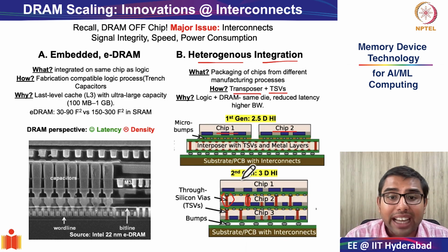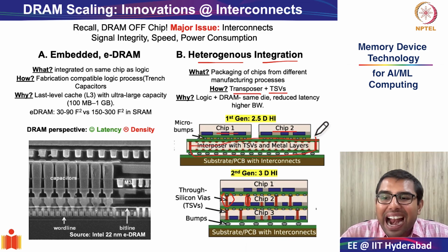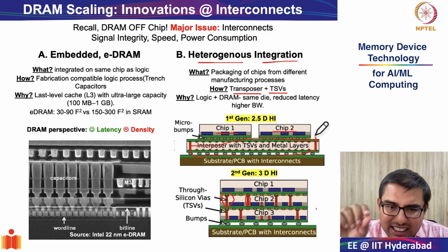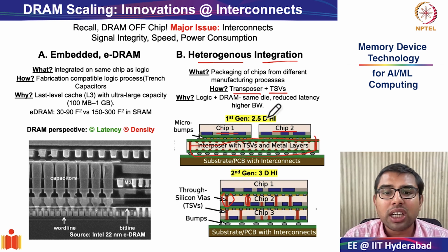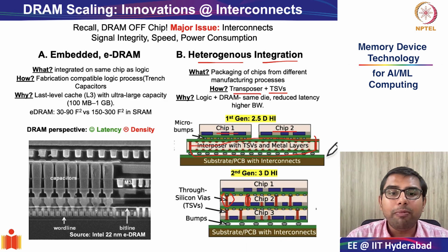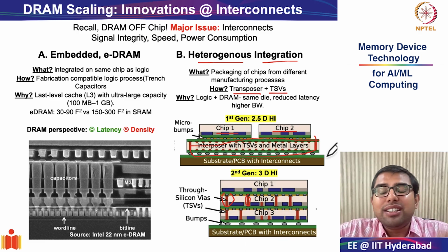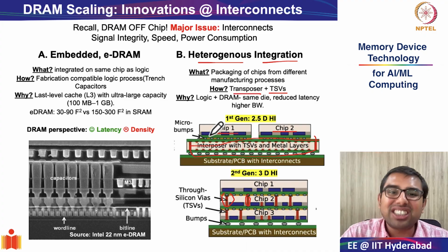And the interposer is basically a common thinned down flat substrate, generally consisting of silicon, that provides the platform to route the signals between multiple chips. So these are your multiple chips, chip 1, chip 2, and you have your interposer layer on which these different chips sit, and through silicon vias connect these chips with each other.